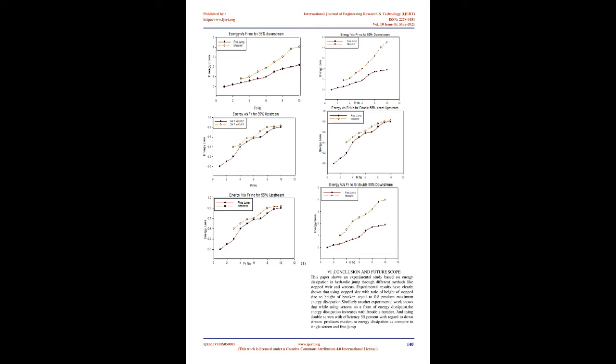Calculation in sections A and B is done by the energy equation, by the energy principle, as a submerged hydraulic jump is forming and the depth at A cannot be measured due to the turbulence, so it is given by Y equals Ho minus V2/2G, [4]. Where Ho is the depth of water before gate.